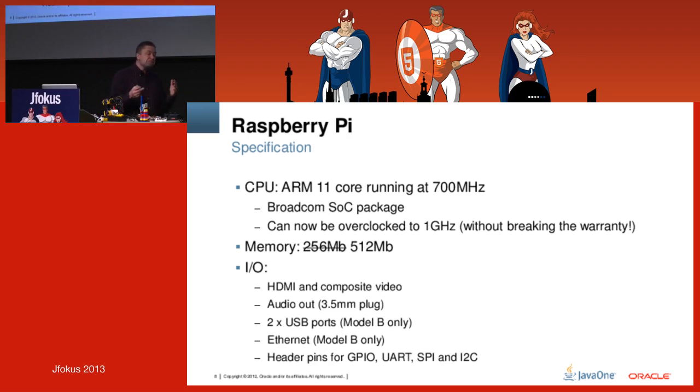And stability might be an issue. Lifetime of the device might be an issue as well. But certainly up to 1 gigahertz seems to work very nicely. I clock mine at 900 megahertz simply because that seems to be a reasonable speed, and I've had no problems at all with stability or anything like that.